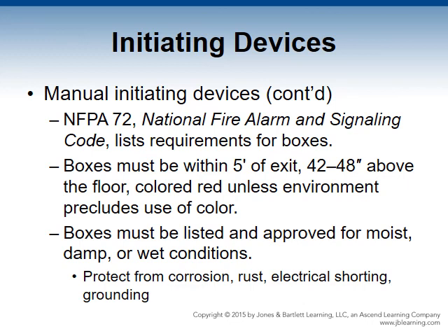They should be red unless the environment precludes the use of this color. In those cases, use an alternate material that makes the box conspicuous. If conditions are moist, damp, or wet, the box must be listed or approved for these conditions. It must be protected to avoid corrosion, rust, electrical shorting, and grounding.